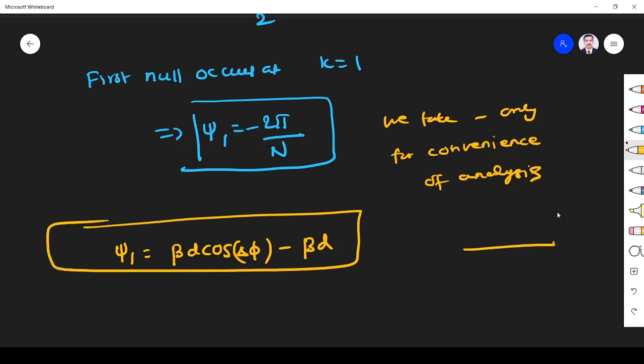Here you see, maximum radiation occurs along the direction of the array axis, right? So the direction of maximum radiation means 0 degree. Clear? This is 0 degree. So the nulls may be occurring anywhere, somewhere here or here. Clear? So that means it is away from that. That distance or angle, let me write del theta, not del phi. I write del theta because we use the term theta only. So del theta. Here only the null should have occurred, or this side, this is del theta, right?